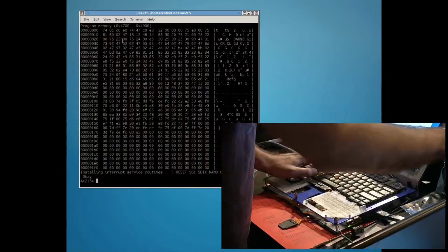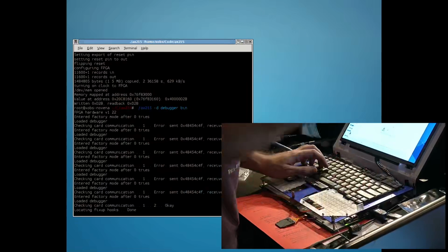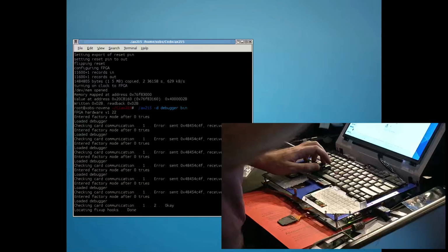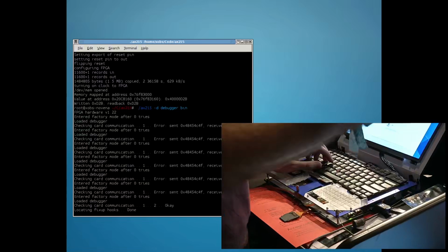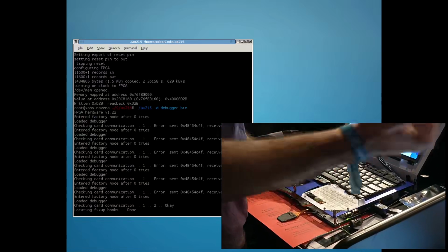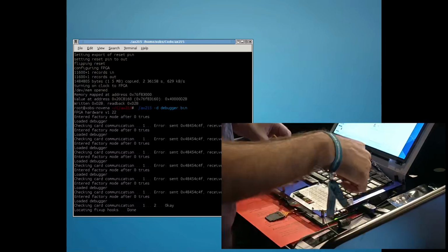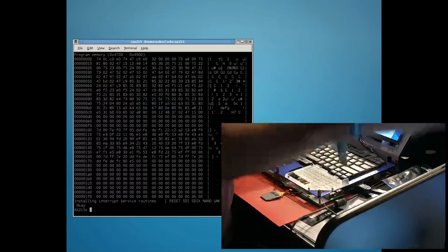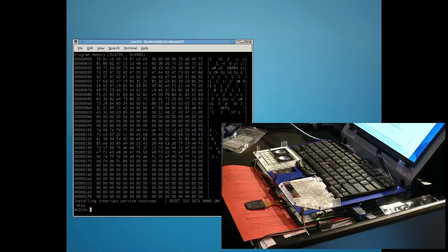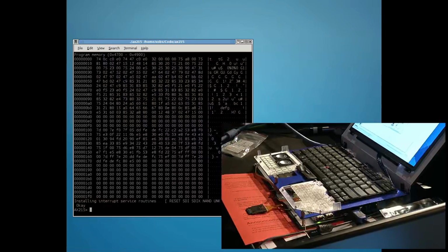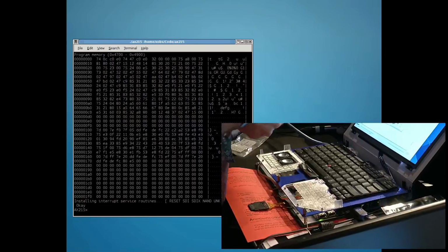All right. So the first thing the debugger does is it tries to knock. You could see because the card wasn't plugged in all the way, there were a few times it tried where it didn't actually communicate with it, but eventually it managed to load the debugger and check the card communication. It sends a random set of packets to the card, and the card is supposed to echo random packets back. Then it dumps the RAM of the SD card. It dumps 512 bytes, which hopefully is our program. After that, it looks through for some fix-up hooks, prints them to the screen, enables some interrupt service routines, and presents us with a shell.